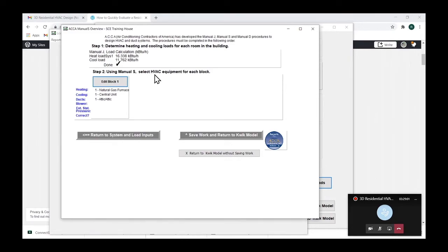Los Angeles versus Las Vegas, okay? So you need to know that. You need to know, will my 3-ton air conditioner meet my load in Los Angeles, or will my 3-ton air conditioner meet my load in Las Vegas? It'll give you two different numbers. So Manual S is a procedure for figuring out how to determine what the actual installed capacity is depending on your design conditions, okay? So one design condition is outdoor temperature. Another design condition is indoor temperature and indoor humidity. Okay, we need to know that. That's usually a default assumption. The other one is airflow.